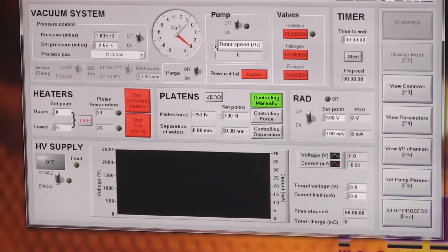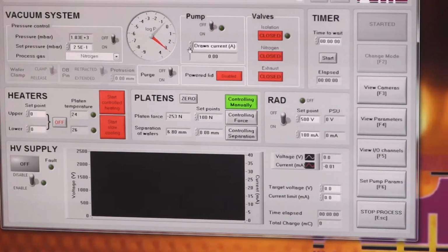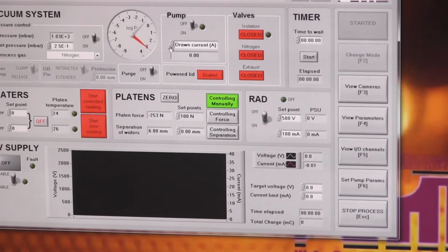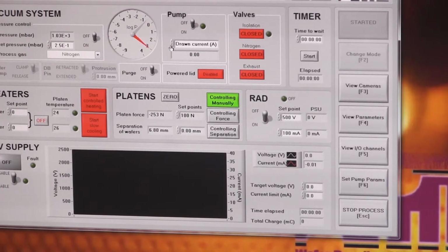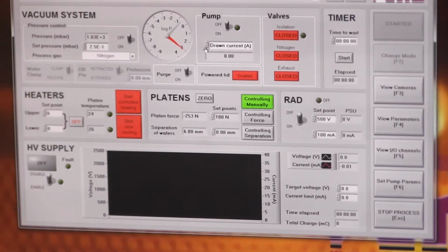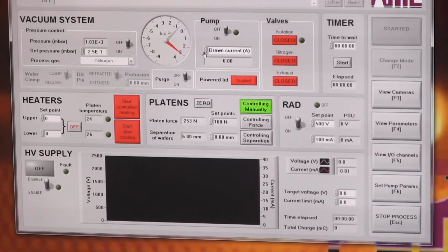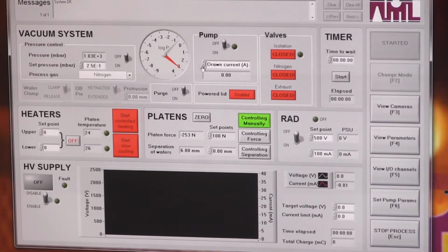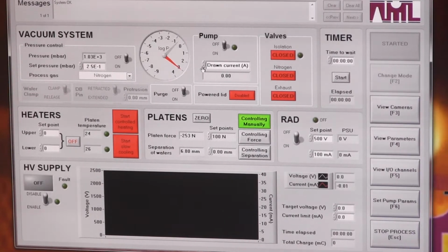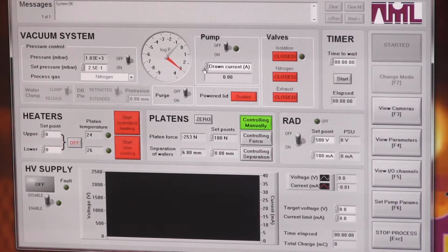You've got 3 options here. We can view the rotor speed of the pump. That has a maximum speed of 1500 Hertz. We can observe the current draw. So what we expect to see is when the pump is ramping up, when it's accelerating, we'd expect to see that up to a maximum of about 3.8 amps. When it's under vacuum and it's just in a steady state, we expect to see less than 1 amp, ideally around about 0.6 to 0.8 of an amp.